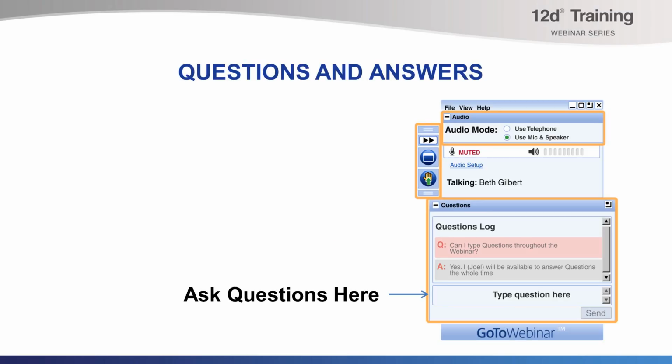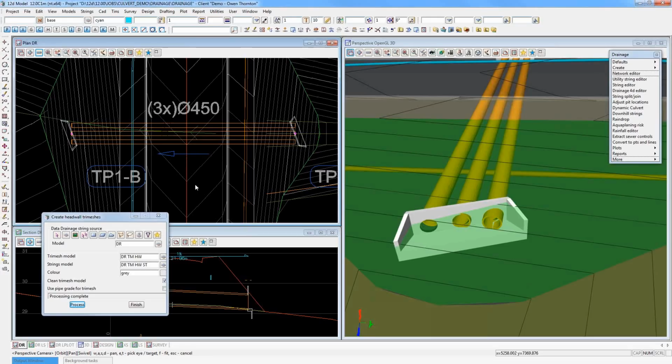Okay, great. Michael in Brisbane has said, can you output quantities of concrete volumes if using cast in situ culverts and base slabs? Well, once you've got them converted to trimeshes, I suppose in theory, yes, if these trimeshes yield a volume, you'll be able to do it that way. I'm suspecting this question might be related to or comparing it with the TMR culvert macro, or the culvert program I should say, which is quite famous for being able to do that.